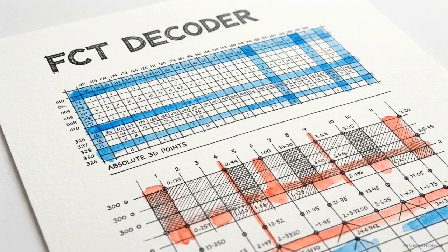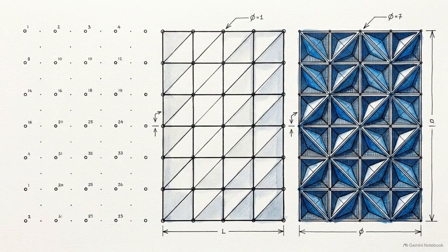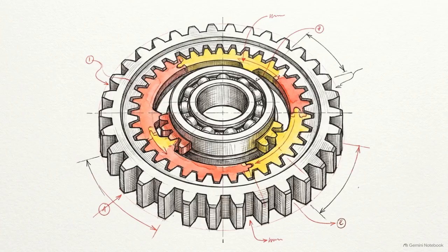Decoding this format reverses the process. The FCT decoder ingests the tokenized tensors and calculates the absolute world space positions of all the stored primal and dual anchors. Using quad reconstruction, vector reorientation, and final triangulation, the decoder connects the primal points to their valid dual neighbors. This fully restores the original mesh topology without ever calculating a global field.